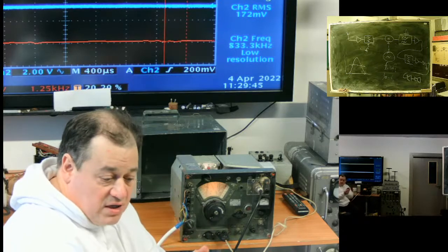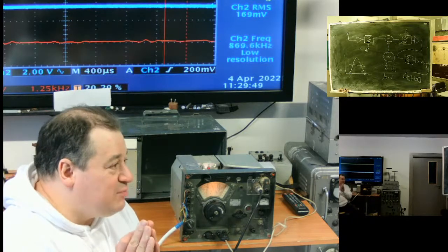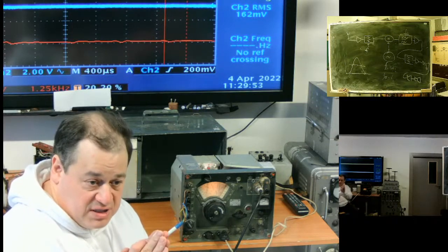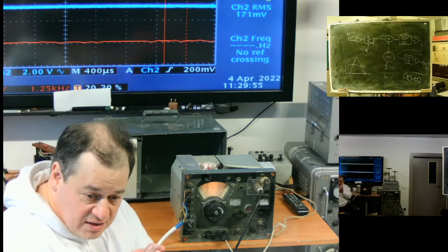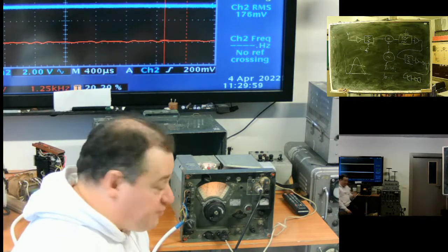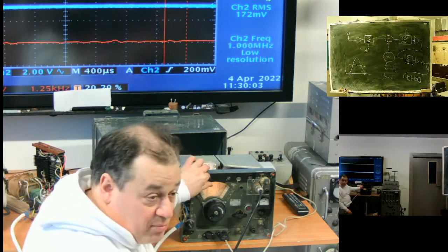For, let's say, a telegraph signal, only a narrow band is needed. The narrower the band, the less influence from outer disturbances, but less information can be fed. For telegraph, only 300 Hz are needed. So I can use a very narrow band.